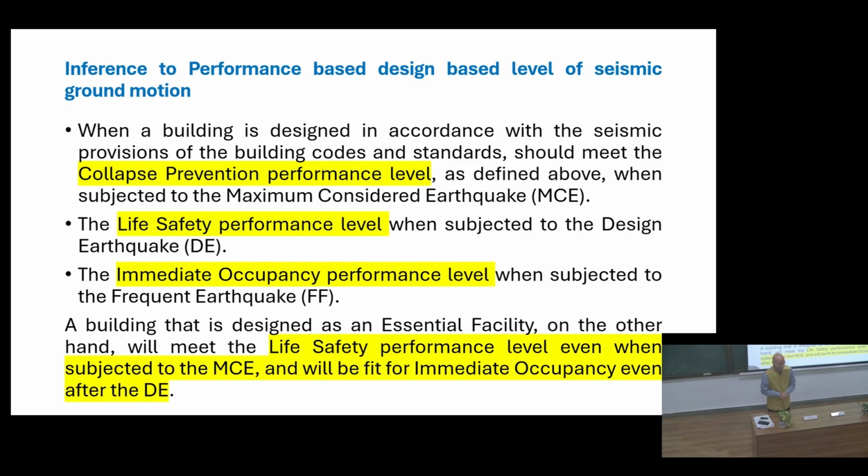Yes. So 0.67 means what? If you reverse it, 1.33, 33%. So that is approximately what it is. It gives a fairly good safety margin of 50%. So 2/3 reversed is 3/2, so the factor comes out, and you still have 50% strength in the structure. If you design for this, that much performance level you expect, but in spite of that, even a higher level the structure is able to sustain. That is why you build in the partial safety factor for load as well as the material.